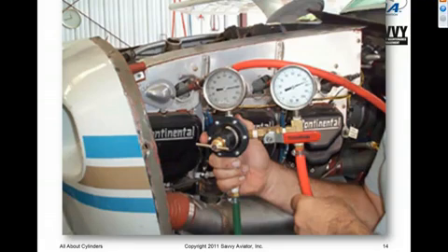So the right-hand meter is always going to read a little bit less than the left-hand meter. In this case, the right meter is reading 75 psi. The left one is reading 80 psi. So we say the cylinder is measuring out at 75 over 80 compression. And again, this is simply a measure of how much air is leaking out of the combustion chamber, at what rate that air is leaking out of the combustion chamber. The faster it's leaking out, the lower the right meter will read.